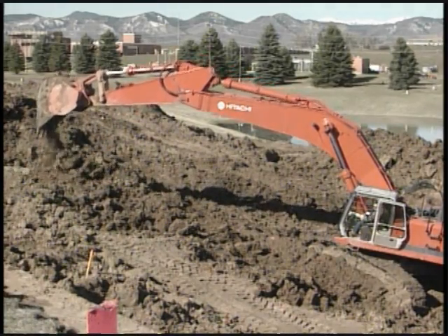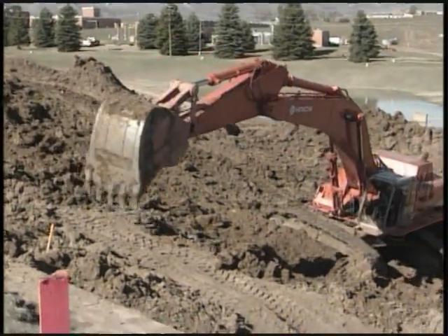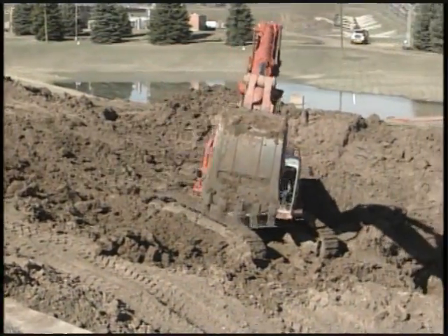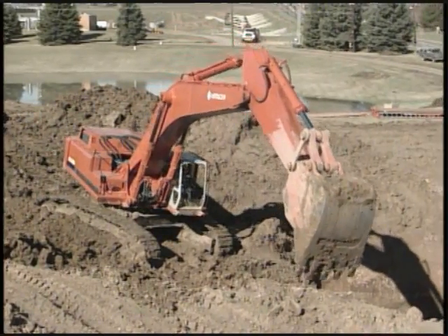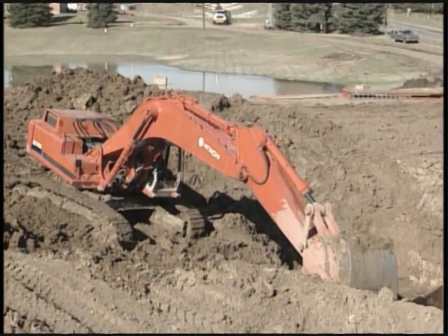It's called the angle of repose, and if workers dig a trench at the proper angle, it won't slide or cave back into the trench. The angle varies with the type of soil, the amount of moisture in the soil, and the surrounding conditions.